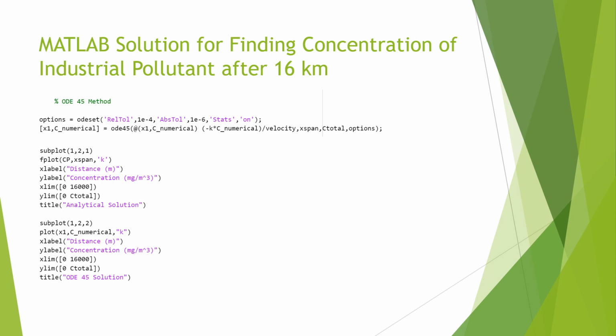MATLAB numbers subplot positions by row. The first subplot is the first column of the first row, the second subplot is the second column of the first row, and so on. If axes exist in the specified position, then this command makes the axes the current axes, which is exactly what comes from the help menu if you look up subplot in this format.